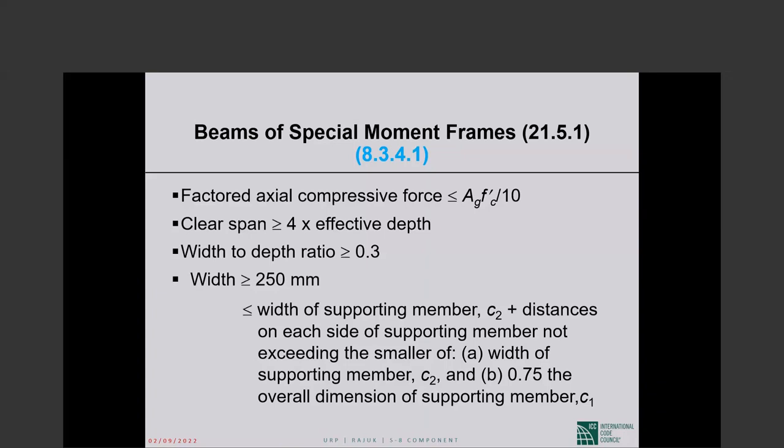When you bring wind or earthquakes into the picture, let's say earthquakes, then the load combinations that you have to consider are 1.2 dead, 1.6 live, 1.2 dead, 0.5 live, in our case 0.2 snow, and 1.0 E, or 0.9 dead plus 1.0 E. Those are your load combinations.